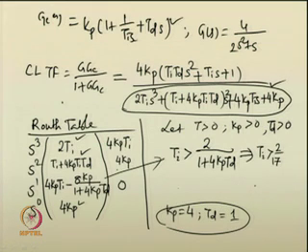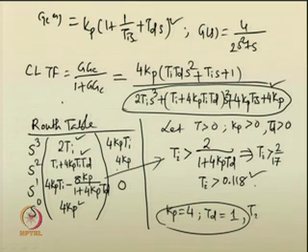that is the same as Ti is greater than 0.118 approximately. So, if we choose a Ti value which is greater than 0.118 with the choice of Kp equal to 4 and Td equal to 1, certainly we will get a stable time response from the closed loop system. Let us assume Ti to be 4, we are far off from this value. So, certainly it will ensure stability of the closed loop system.